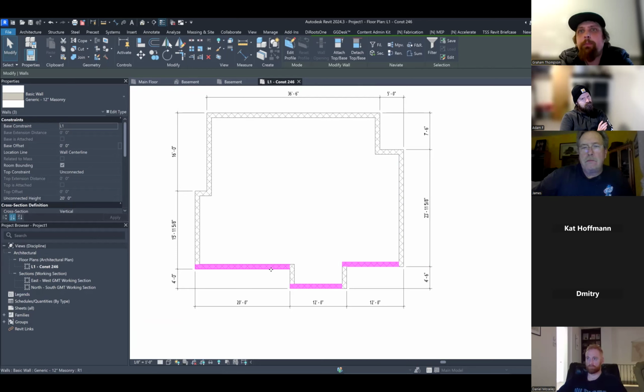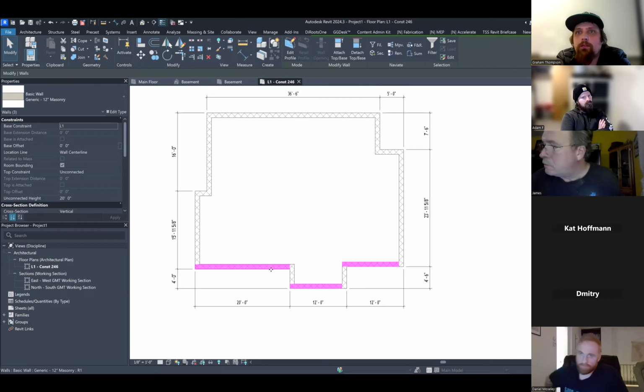I could, but again, drag and move is a lot of guess and check, in my opinion. You can get things close, but getting things right on is hard, especially when your dimensions report in 1/16 of an inch increments and Revit models to the 256th of an inch, right? So there's a lot of slop factor when you drag something.